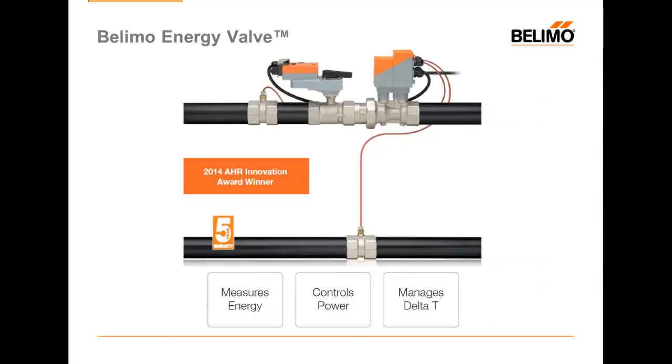If you're new to the Belimo energy valve, the Belimo energy valve is a pressure-independent valve with a fully integrated BTU meter. This valve allows us to do a lot of extraordinary things, including measuring energy, managing delta T, and what we're going to discuss today, how to control directly to power output into your space.